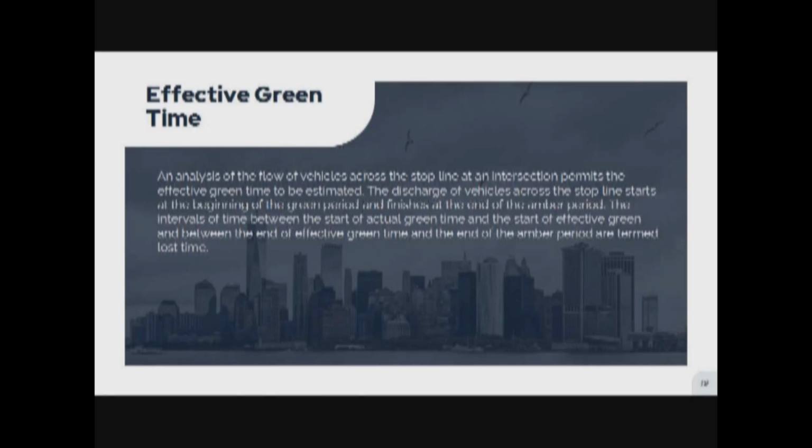Then we move on to effective green time. Effective green time is defined as the length of time that would be required to get a given discharge rate over the stop line if the flow commenced and finished simultaneously and instantaneously, in passenger car units per hour.